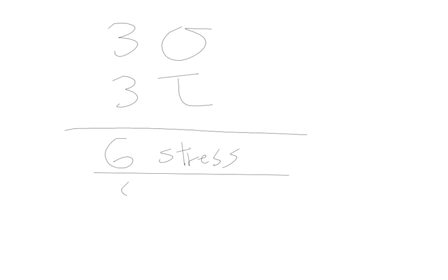Those values are sigma x, sigma y, sigma z, tau xy or tau yx, tau yz or tau zy, and tau xz or tau zx. These are 6 distinct stress values at a single point. So it's not 18, it's just 6.